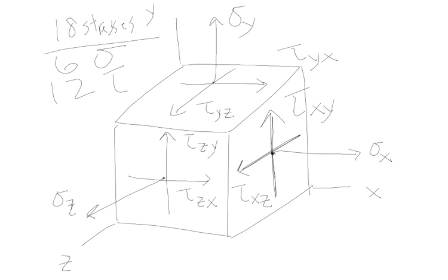What you can do is apply those 6 equations of equilibrium to this cube. Obviously, these are stresses or pressures, but they can be converted to forces to apply your equilibrium equations. You simply assume a unit area, assume that this cube has sides of 1, so all your areas are equal to 1, and then you multiply all your stresses by the areas to turn them into forces. That's very easy to do. Then you apply your force and moment equilibrium equations, and what you're going to find is this.